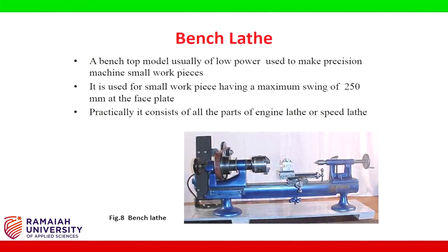Bench lathe. A bench top model, usually low power, used to make precision machine small workpieces. It is used for small workpieces having a maximum swing of 250 mm at the face plate. Practically, it consists of all parts of an engine lathe or speed lathe.